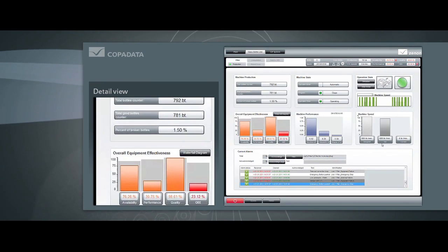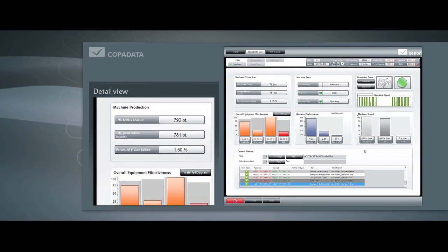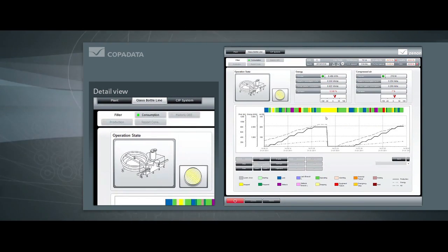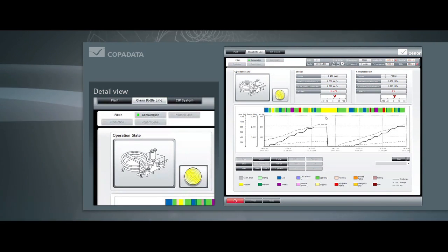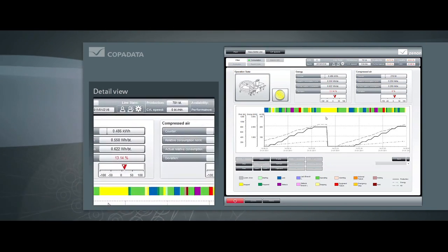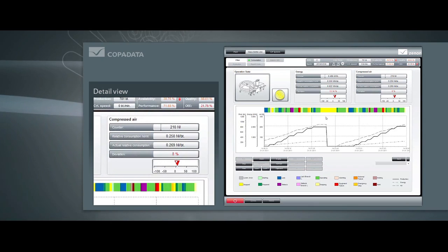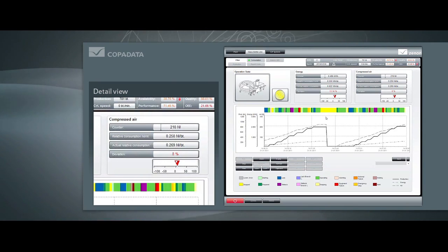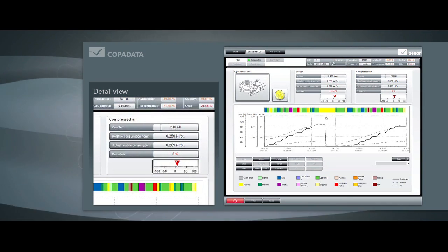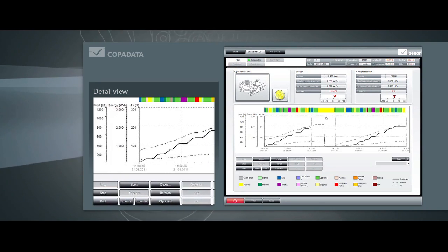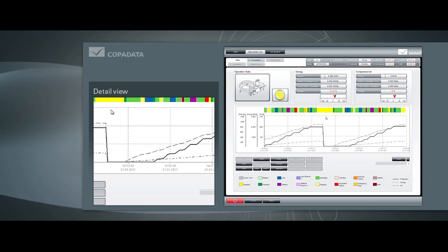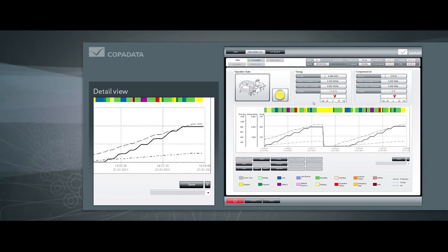As mentioned, zenon supports the production team not only to improve the effectiveness, but also to optimize the consumption. We keep the focus further on the filler, this time from consumption management point of view. For the used resources, in our example energy and compressed air, the relevant information is made available. We can see absolute consumption, relative consumption, and the comparison with the consumption norm. A trend display enables to see the correlation between the consumption evolution and production information, as key for identifying the causes for consumption variation out of the normal limits.